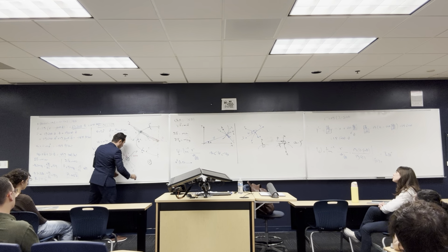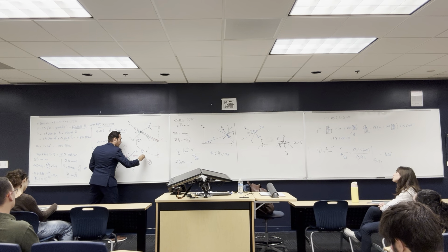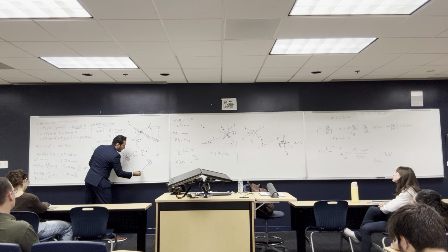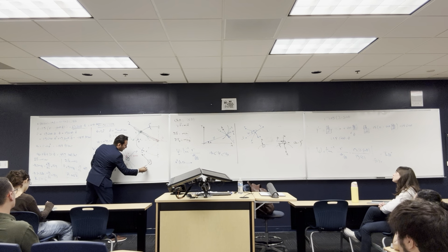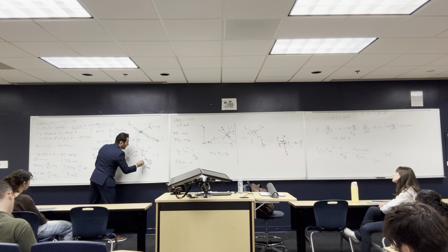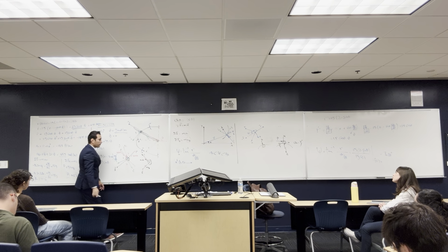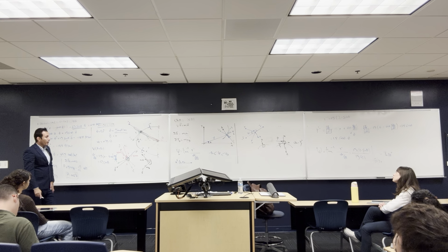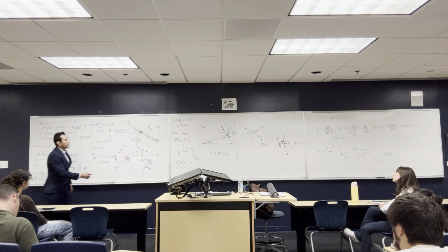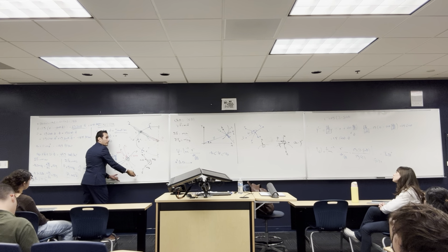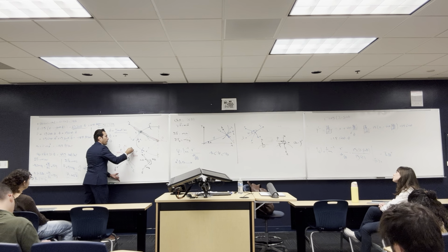Like, I know that this body is this way. I know that r has this direction, and theta has this direction, and this is the direction of m a theta, and let's assume this is the direction of m a r. That is the direction of my acceleration. Okay? All right, that's what we call the kinetic diagram. But the most important part is the free body diagram.